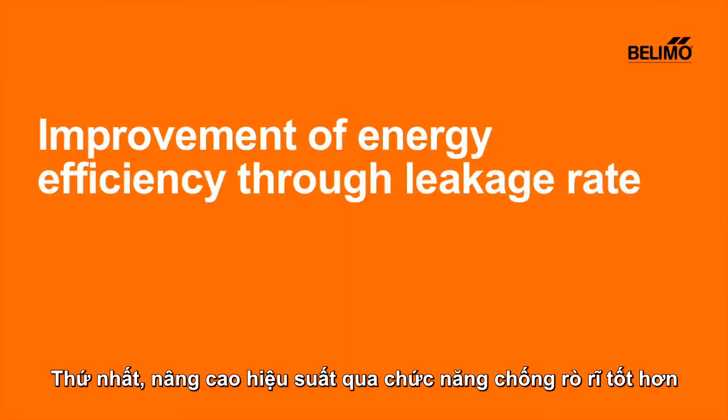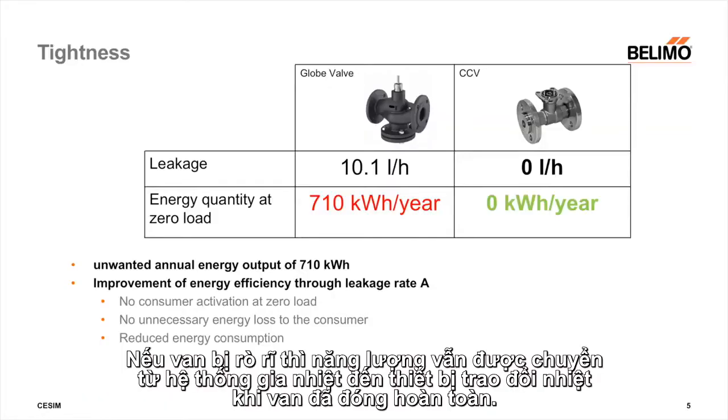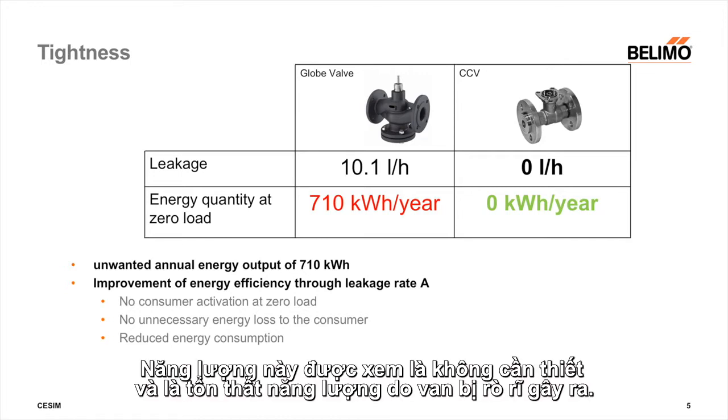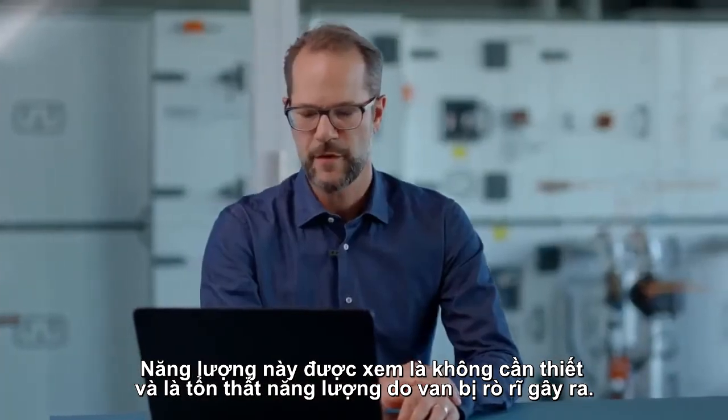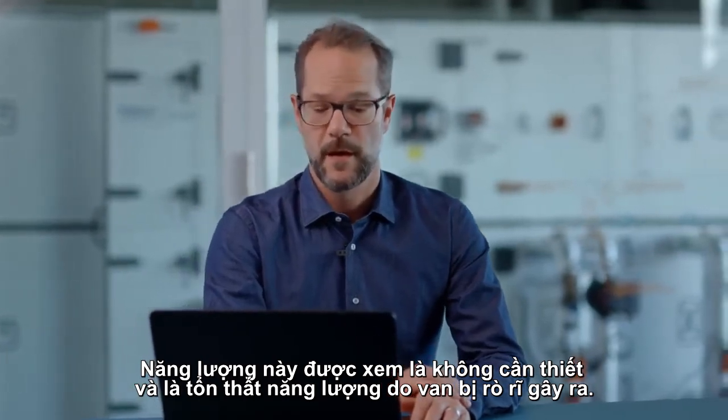Improvement of energy efficiency through a better leakage rate. If a valve leaks when closed, energy is transported from the generator to the heat exchanger. This amount of energy is delivered to the heat exchanger. It can be assumed that this energy output is not required if there is no flow or power requirement from the valve. This amount of energy, therefore, can be regarded as a loss.